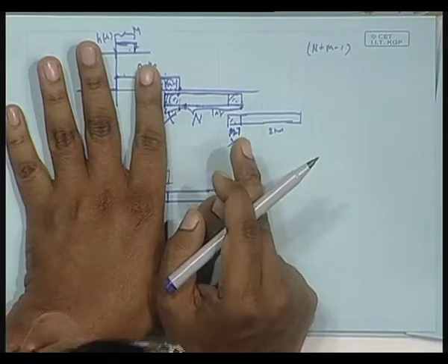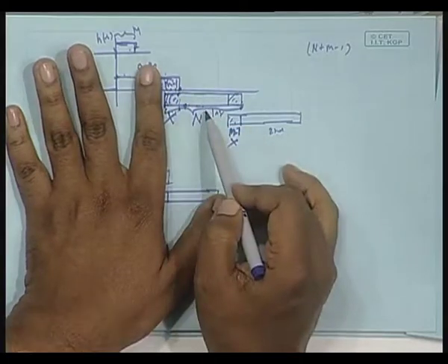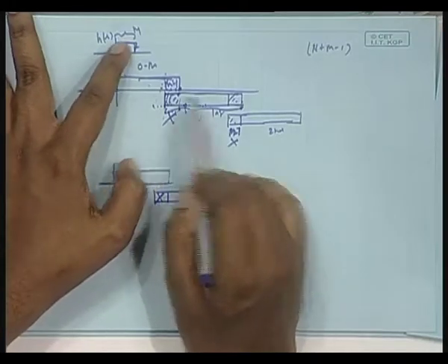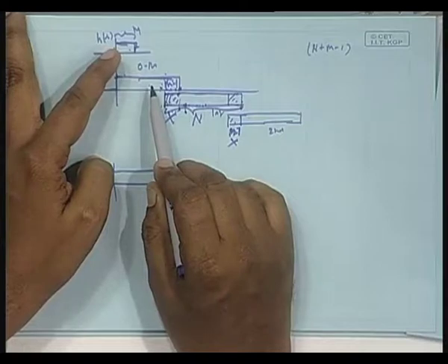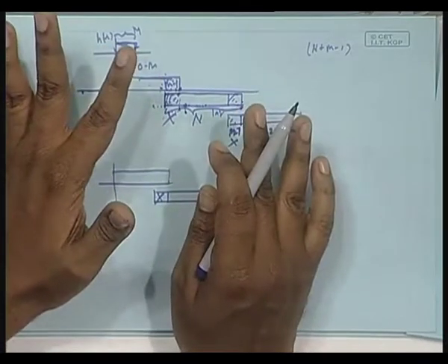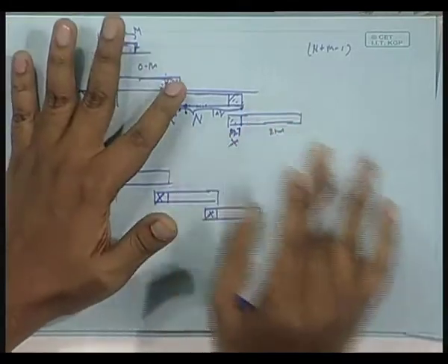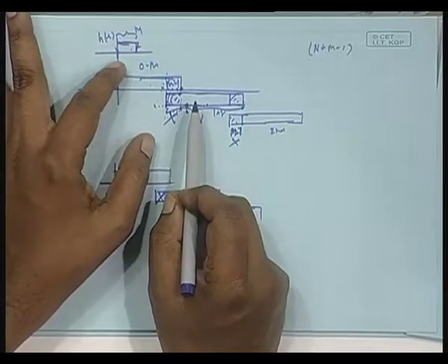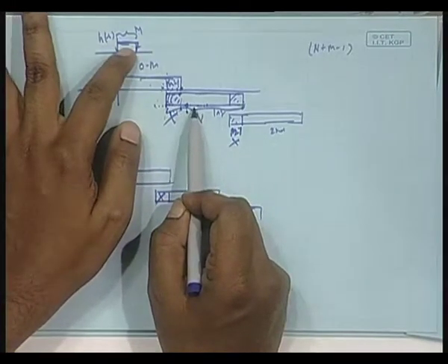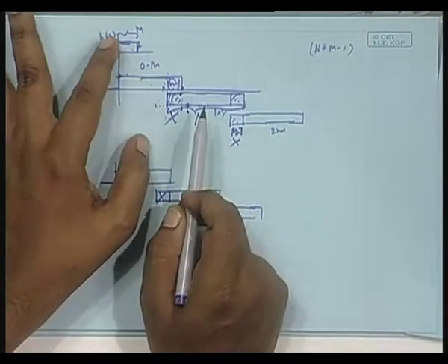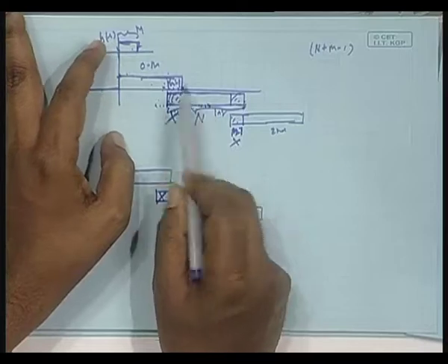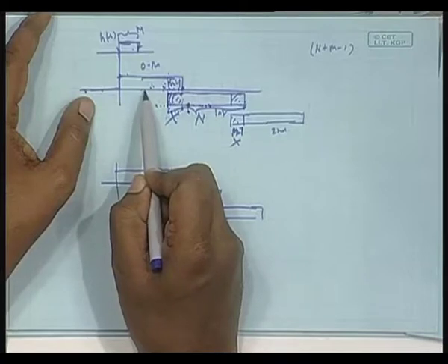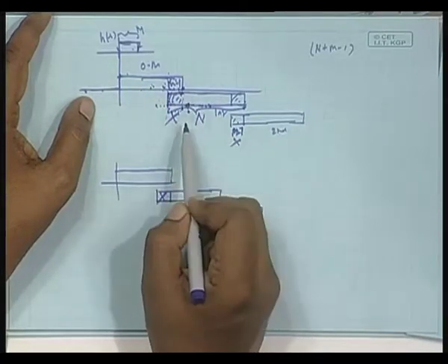From the mth point you get the real linear convolution result between this block and this block, and that is what I want, because from this point onwards convolution between this and this is enough, I do not need any data from here, isn't it. So, two things are matching. There are also m minus 1 points you have to ignore, and I am already ignoring. Afterwards, you get the real linear convolution output between this and this, and I am interested in that linear convolution, because at this point, at this point, at this point, when I convolve, even when the data is contiguous, there is no contribution from this tail. This much is enough. Are you following me?